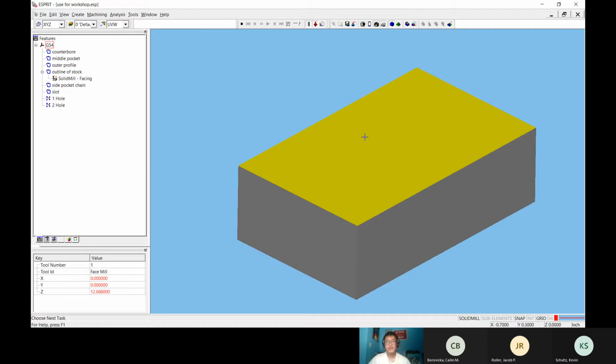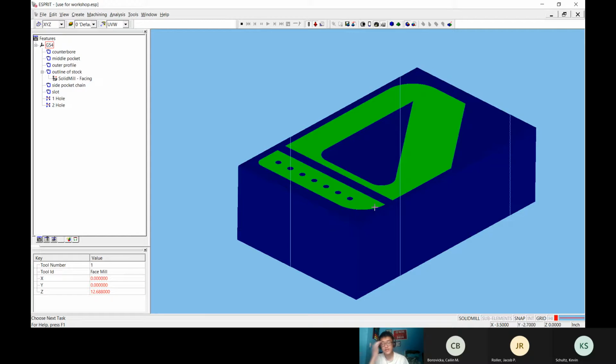Okay, that's good. Another important thing to do when you're in a simulation is check for your tolerances. You can use this button called comparison, which is right here. It's like a slanted part with some colorful rainbows on it, and you click on it. Each color has a different tolerance. So if it's green, that means it's within 0.02 of an inch of the part, and other colors have different tolerances.